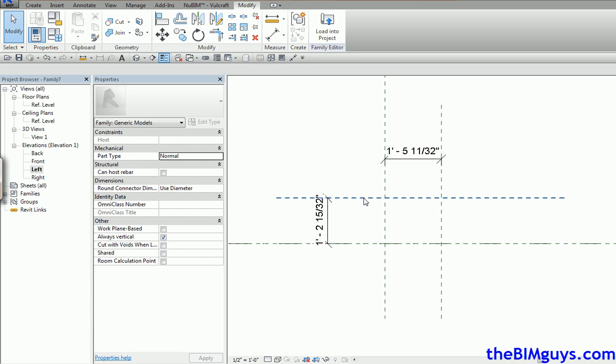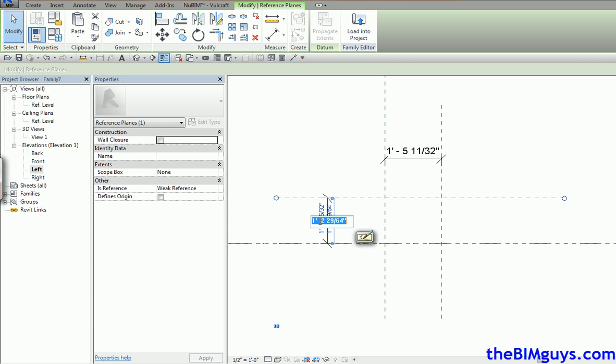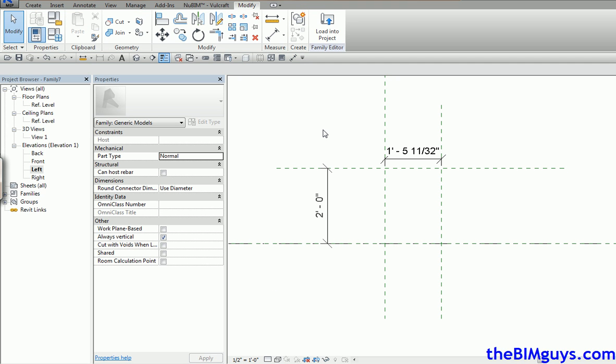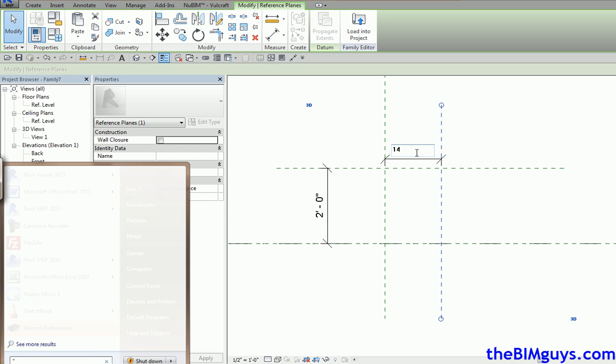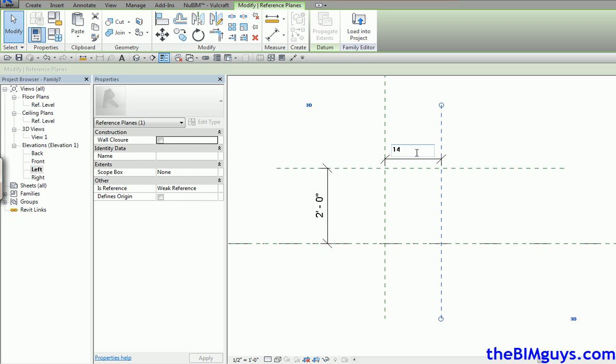Now to verify the right height, it is a 2 foot overhang, so I'm going to set that to 2 foot. Okay, 7 on 12 roof, so 7 times 2 feet would make this 14. So we grab that dimension, set that to 14 inches. That is going to set us up. That is our angle.